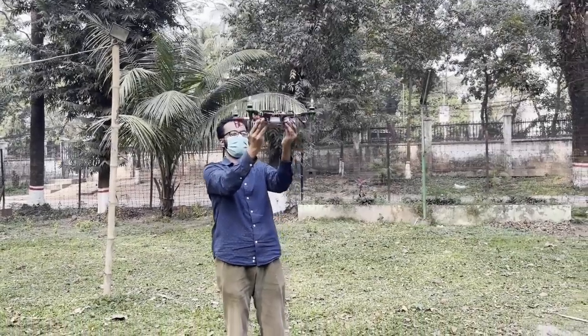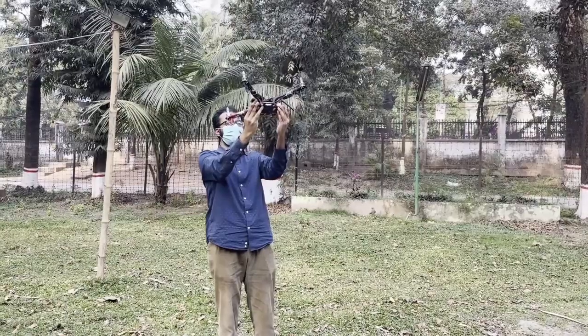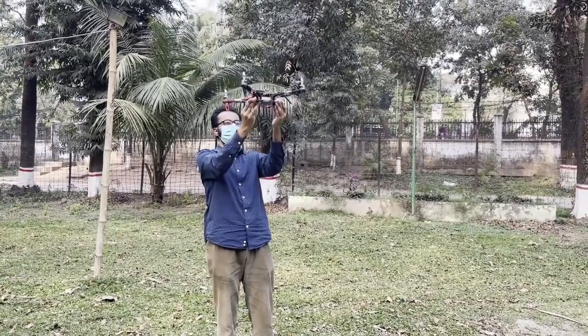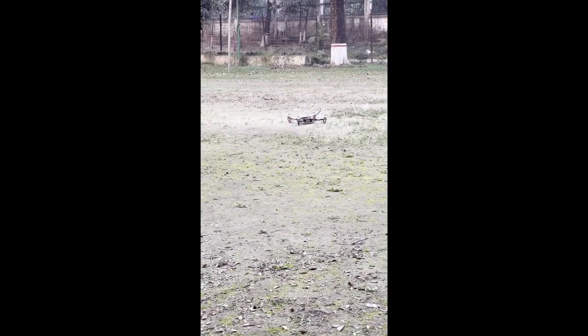In the next clip, we can see our group member trying to balance the drone while it was correcting itself using PID. But due to vibration, our gyroscope was generating garbage values, and the PID corrections were being extreme in one direction at one time and then in another, which is why it was constantly proving difficult in earlier and later trials to balance the drone in flight.